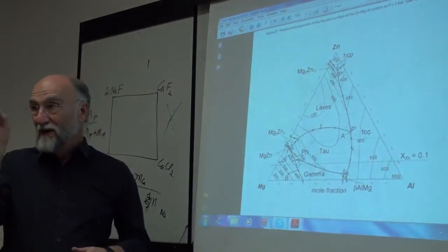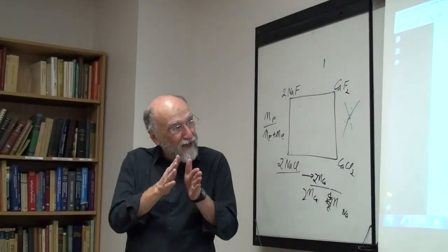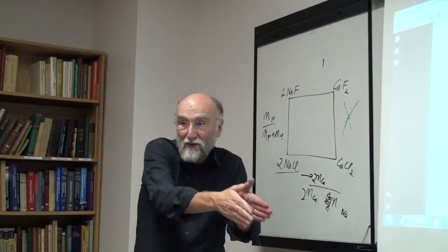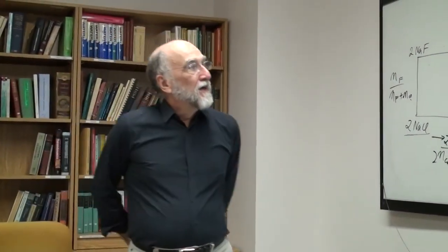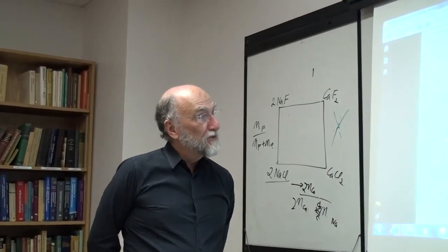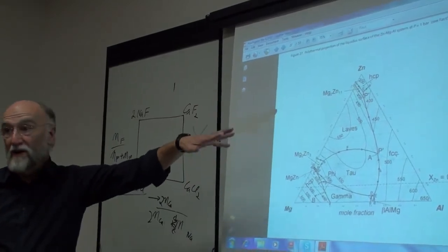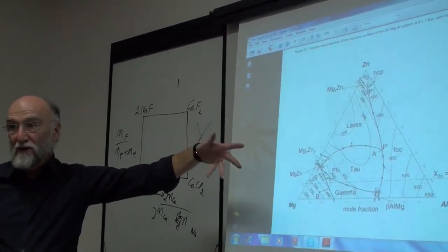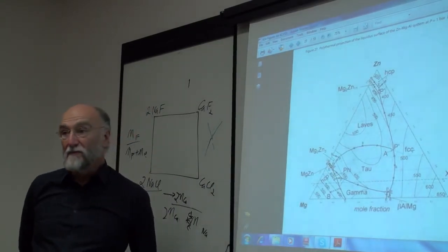You do like a double. As you follow a zero phase fraction line, you're doing a double zero phase fraction line, keeping the amount of both solids exactly zero as you move along. So it's the same sort of principle. So with FactSage, if you ask for a polythermal projection, it asks you two things. Do you want the isothermal lines and do you want the univariate lines? Those are two separate calculations. Sometimes the univariate line calculation can take a long time.